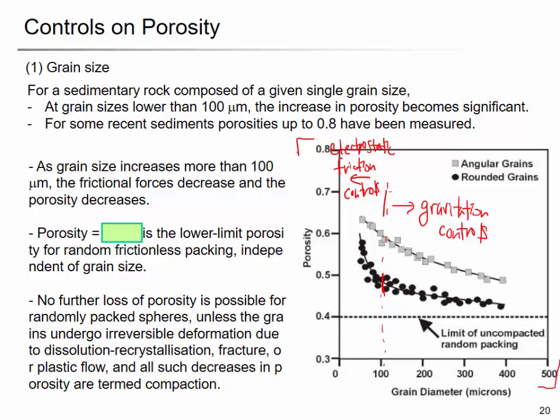Number 200 sieve has the opening size of 75 micrometer. Right? So 75 micrometer, we use that number to differentiate the fine grain soil and the coarse grain soil. Right? And fine grain soil has heavy influence by this surface relative force.